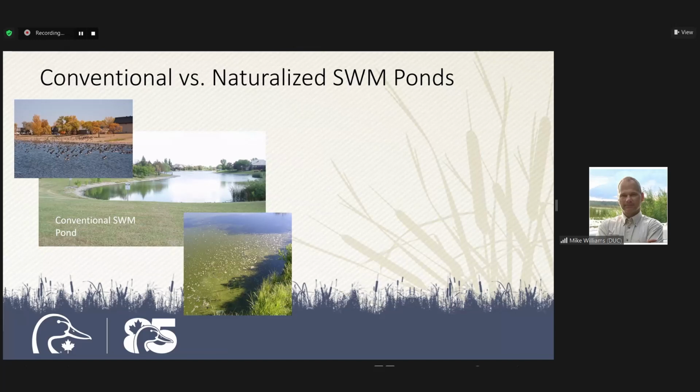So at the NSDF site, it's designed to handle its non-contact surface water runoff with a series of 3 surface treatment ponds, as Craig mentioned, before being released to Perch Lake. With regard to surface water treatment ponds, there are conventional designs like what you see above in the photos, with very little in-basin vegetation and mowed turf grass in the uplands. These sites can have numerous issues, including poor water quality, toxic algae blooms, and they attract grazing Canada geese, which further degrade the water quality with their droppings.